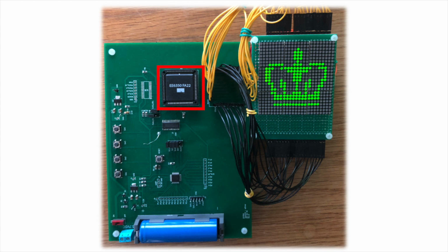Here, our chip is shown on the top of the board. When the board first boots up, the program on the microcontroller starts the clock at 1 MHz. Then the reset is asserted for a few clock cycles. After that, based on the demo selected using 4 keys on the board, the microcontroller starts to send data to our chip. Note, we have used standard SPI bus protocol to transfer data, and the SPI clock is the only clock used by our chip.